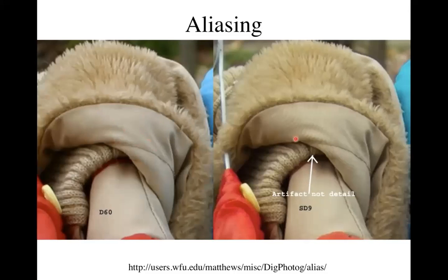In this camera, the CCD image detector, the array of detector elements, is sampling at such a frequency combined with the optics such that you get aliasing of this low spatial frequency pattern on top of your image. And this is in fact aliasing of the power or the energy of the high frequency of the pattern back into the lower frequencies that are displayed, and you get this artifact. It's called a moire pattern, and it's an example of aliasing.